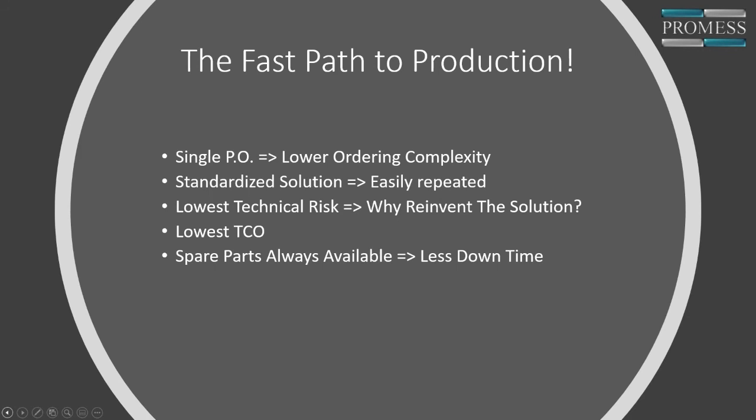How are they clamping the input and output shafts? That's a good question, and one that comes up quite often in these applications, and there are multiple ways to do that. I have seen electric and air collets used to couple around the inside of a shaft, where you need to engage inside of it. I've seen spline shafts mounted to the end with different types of couplings to the output shaft of our units.